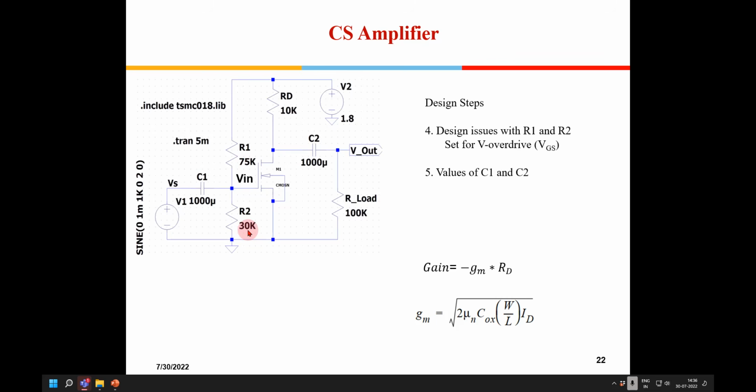So what would be the advantages, disadvantages? Can you think of something? The current drawn. Yeah, see, the current which is flowing here is waste, right? I just require a potential divider here. So if I put 7 ohms and 3 ohms, large current will flow here. It is of no use. Then why not put mega ohm and mega ohm here? Mega ohm and mega ohm will cause particular problems. The first problem is size and heat.